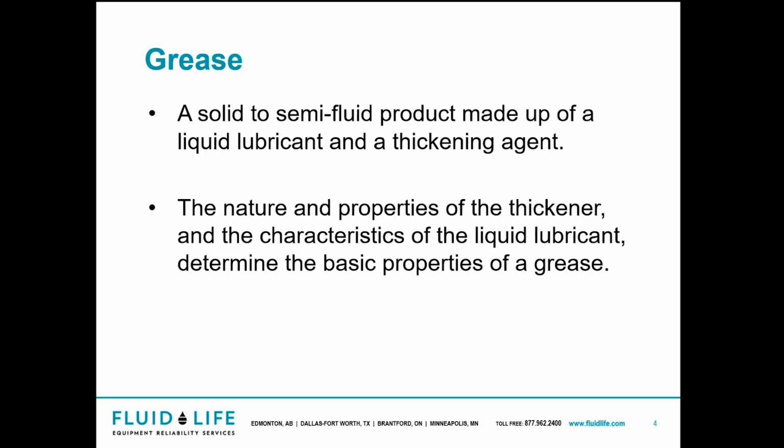Now, where we see most of the grease applications is in bearings. So whether it's pins and bushing type bearings in mobile equipment, or roller element bearings, or something along the lines of fixed equipment, for example, an electric motor. Greases are very effective at moderate to low speed, not so much at high speeds. The reason is that the thickener and the lubricant can separate at high speeds. Now, yes, there are coupling greases and all that, but those go beyond what we cover in this short little course.